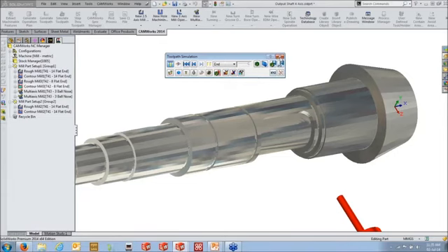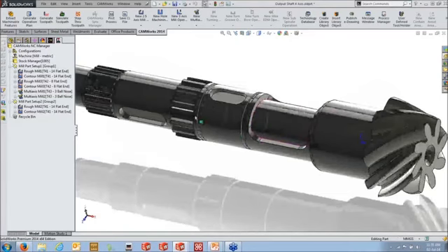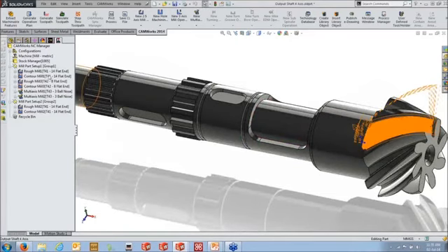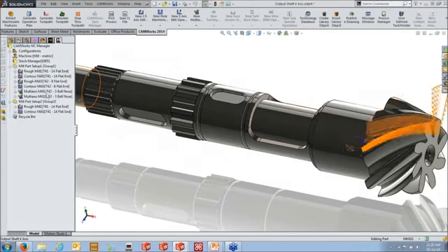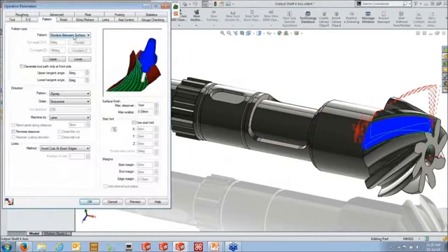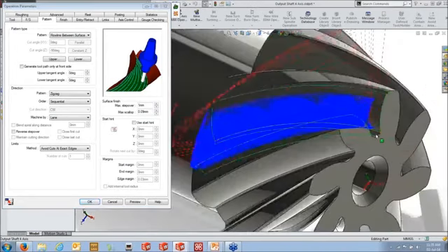Perfect. And you can see there's a lot of parameters in here. I just used one of the default 5-axis strategies. We went in, we changed the pattern type in here, flow line between surfaces, using the upper surface here to drive between the lower, using the edges and the radiuses down here.